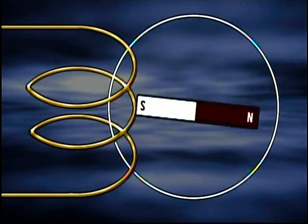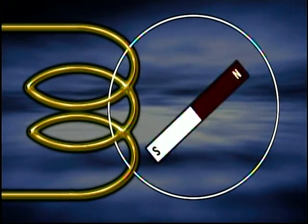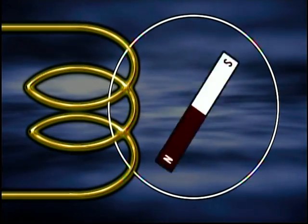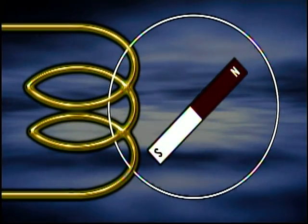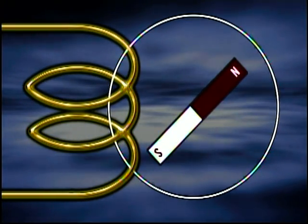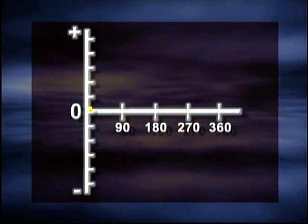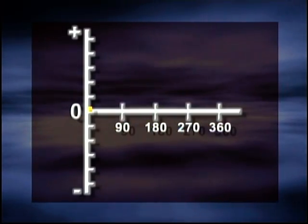As the magnet in this generator is rotated counterclockwise, the magnetic north and south poles cut across the coil, inducing a voltage and causing current to flow in the coil. The voltage output is 0 when the coil is not being cut by any magnetic lines of flux. This is plotted as 0 voltage at the 0 degree point on the horizontal axis.